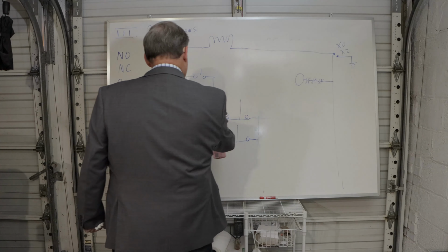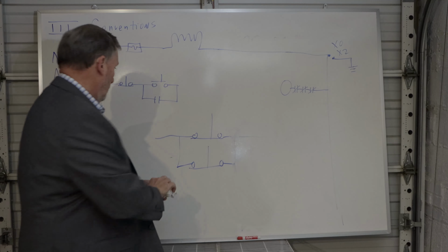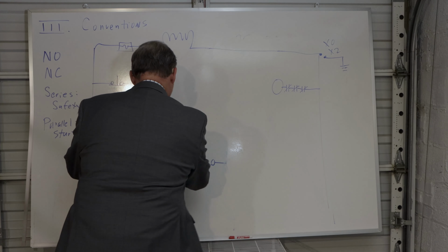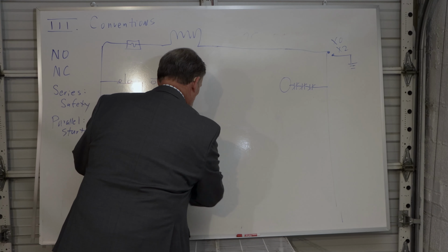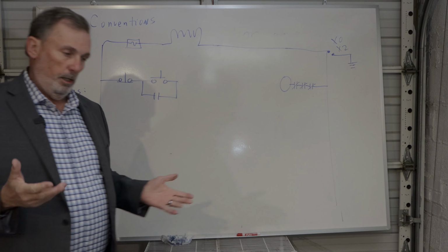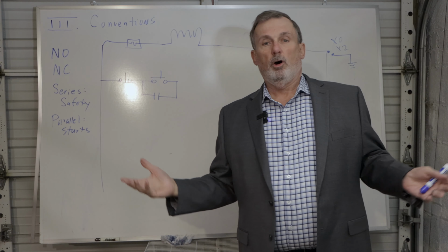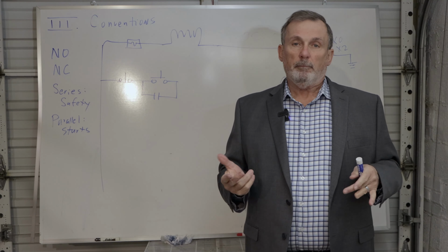Next item we want to look at is indicating lights, another convention. Everybody on their control panels wants to know if the motor's running or not.